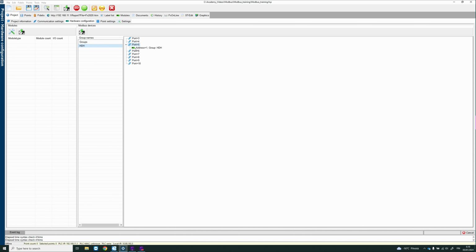Here we have address 1. Add a type for all the devices. For example, we need a coil starting from 0 with a count of 4. Click Coil Start 0, set the register count to 4, and the timeout can be around 150.